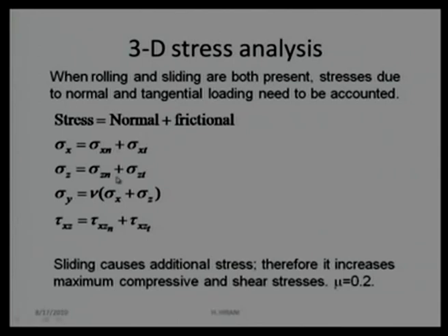Now, in this case, whatever results I am going to show, it has been assumed the coefficient of friction is 0.2. Whatever normal force we are applying gets multiplied by 0.2. Our overall force is 1.2 times the normal force, but the directions are different. This is along the z direction, this will be along the x direction. So a simple 1.2 times calculation may not give all the results. We will take a vector assuming the directions, and calculate the force according to the different axes.